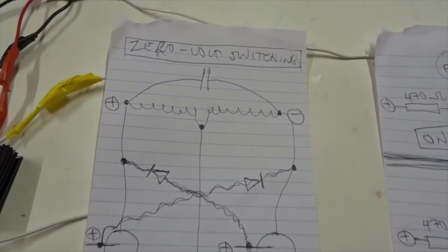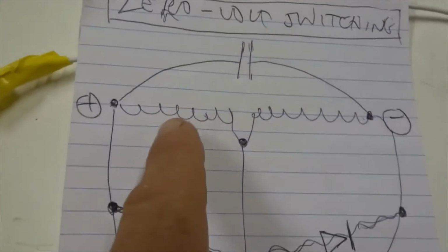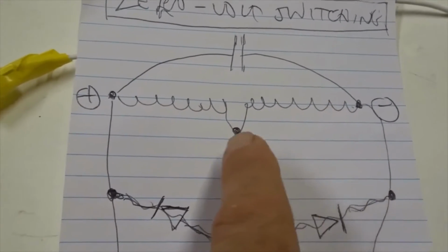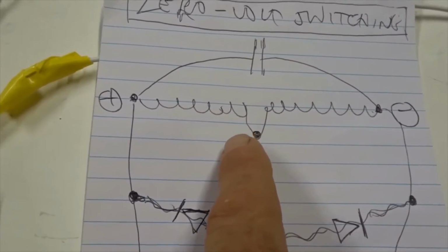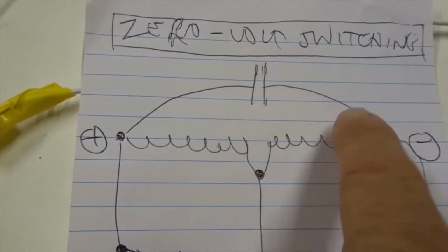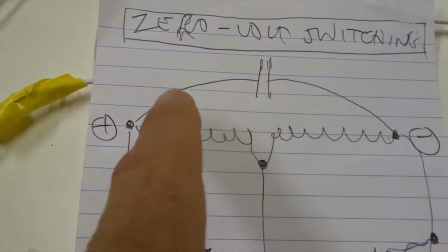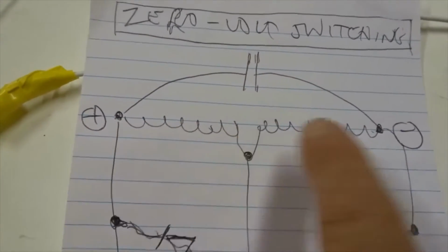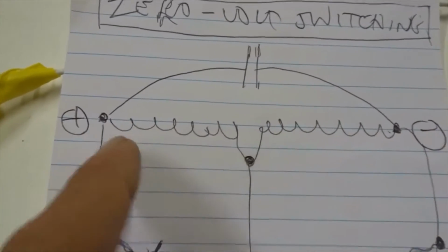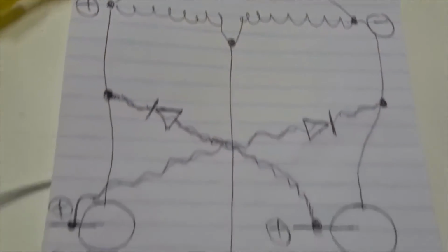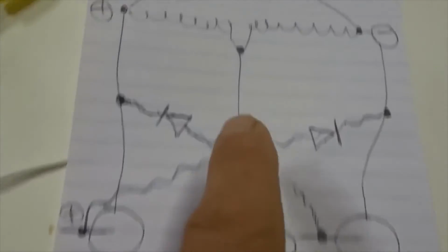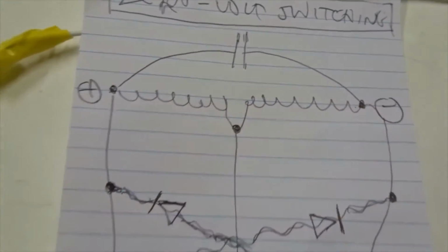Now in the standard circuit known for 0 volt switching, ZVS, we have a coil here which is tapped in the middle, the primary coil, and a capacitor in parallel with it to help the oscillation and control the frequency. It can flip back and forth plus minus on both ends of that coil, and it starts plus in the middle, goes to the center, and then it can go plus minus on either side.